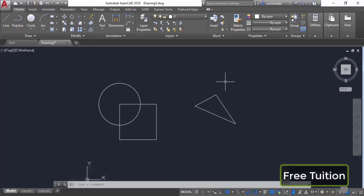In order to convert it into region, you can use its command equivalent, that's region, or you can go to this draw panel, expand it, and select the region tool. Now I'll select this region tool, and now click on this circle and press enter. So now this object has been converted into a region, although we still have the circle just right behind this, but we now have a new object also here. Now here in this case, we have a simple polyline. Let's convert this one into also a region. So I'll select the region, I'll click on this and press enter. We again have a new region here.